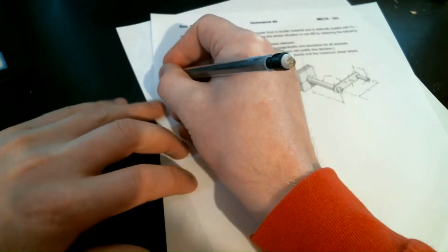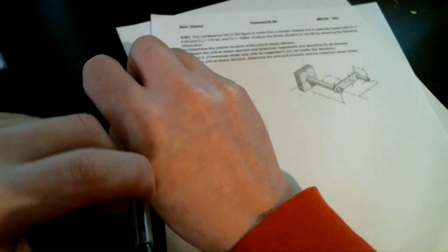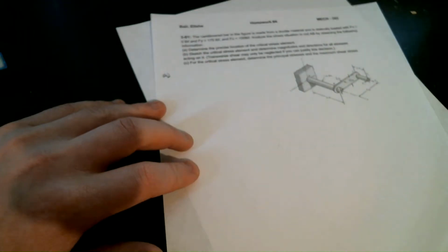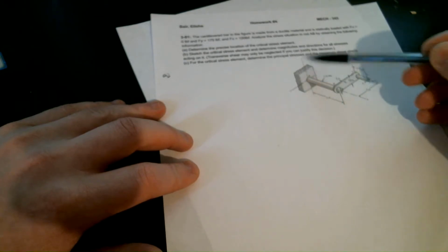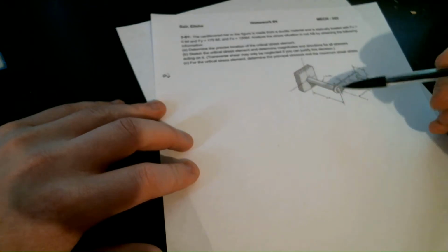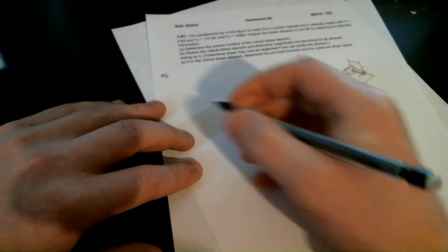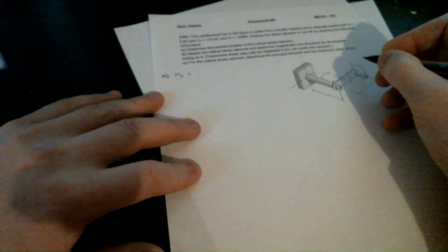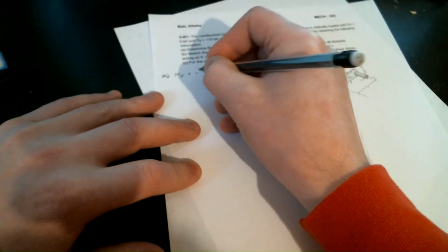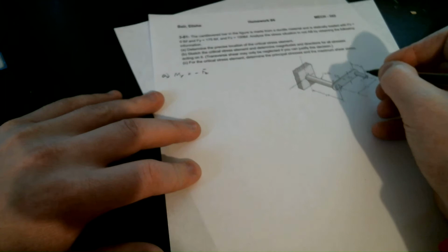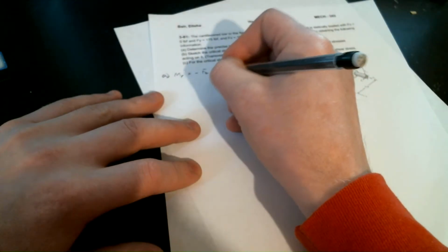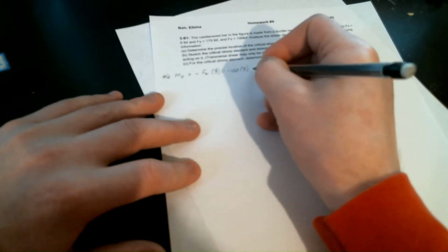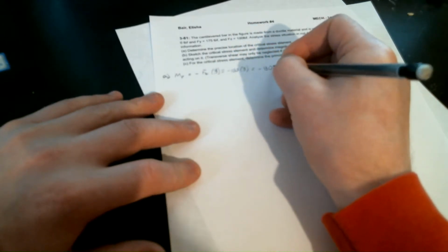So we have to do part A. The first thing we need to do is find the moments. We can do the moment about the y-axis, and the force that will rotate it around the y-axis will be Fz. So the moment about the y will be negative Fz, times 2 plus 6, so times 8. That will equal negative 100 times 8, which equals negative 800